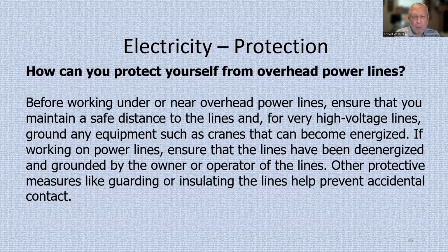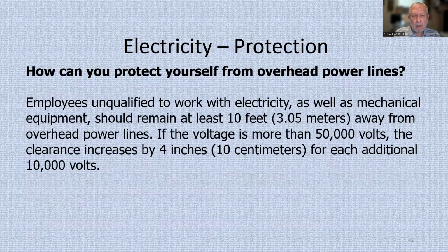Before working under or near overhead power lines, ensure that you maintain a safe distance to the lines, and for very high voltage lines, ground any equipment such as cranes that can become energized. If working on power lines, ensure that the lines have been de-energized and grounded by the owner or operator of the lines. Other protective measures like guarding or insulating the lines help prevent accidental contact.